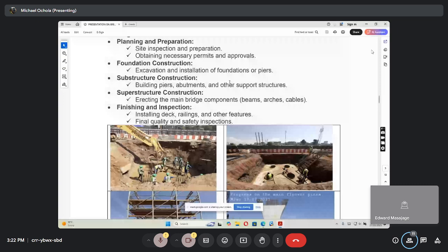Okay. So this is the batching area where these are what we call stockpile bays. You have different grade sizes. You separate them so that they don't mix. You only mix them when they're already in the batching plant. So this is how you can see. As a construction manager, you also need to know where to place it. How do you access it with a dumper? Where do you pour material? How do you move the concrete batching and the truck? This is also security, yes, safety. Many things do happen. You can see they've done it. So this is small, even the site office is there. How do you do it? So at construction, there's quite a lot you do.